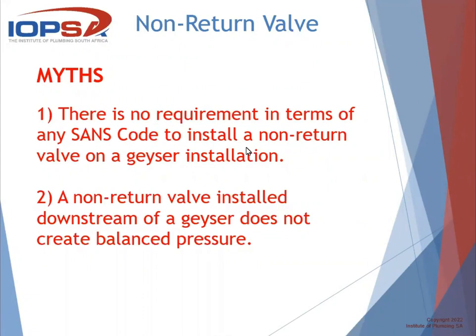And oh, it's the pump, so let's switch it off. Then they switch it off and leave it off and live with the non-immediate hot water at the furthest point, but then start wondering why their water starts to taste and smell foul, because they've got stagnant water in this loop.